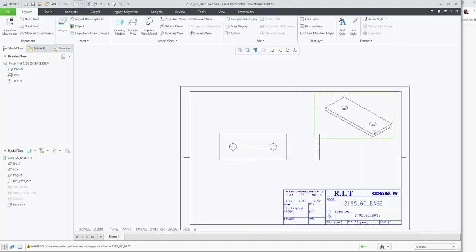All right, no center lines in the isometric view, just in your orthographic views. Only need two views for something that's a uniform thickness, so we'll clean it up, get those center lines in, and move it in the right place.